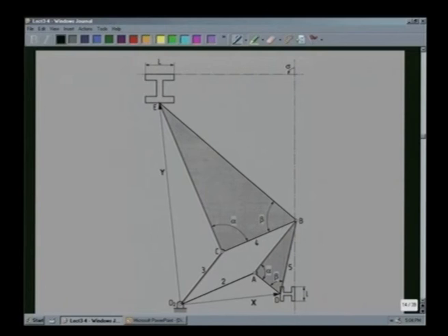This diagram shows the kinematic diagram of the model of the mechanism which we have just now seen, that is, that copying mechanism or plagiograph. As we see in this mechanism, we have 5 links. One is the fixed link, O2A is the second link, O2C is the third link, BC is the fourth link, and AB is the fifth link. So, it is a 5 link mechanism. So, let us say N is equal to 5.